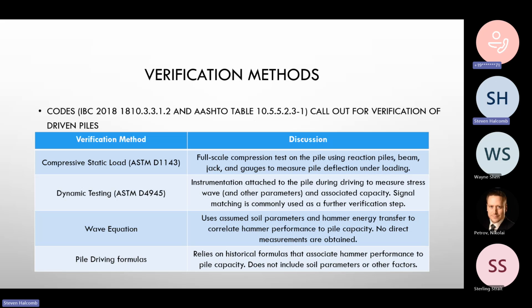And then you have the pile driving formulas, which have been around ever since piles have been around. You just figure out how much energy, what's the weight of the hammer, how far you're dropping it, and how many blows per foot, and back calculate what the capacity should be based on your observations.